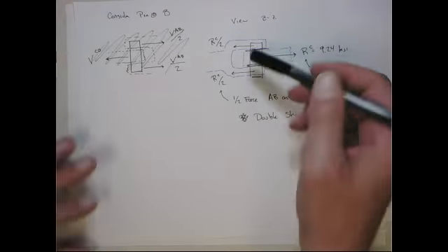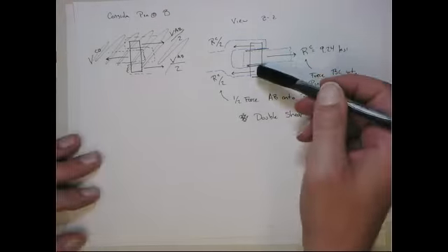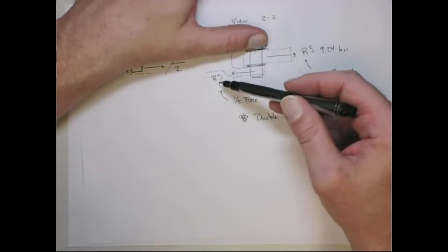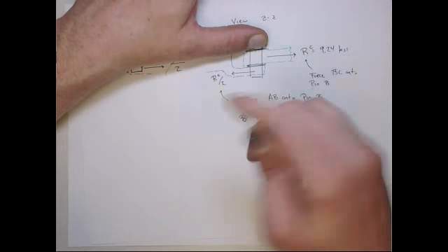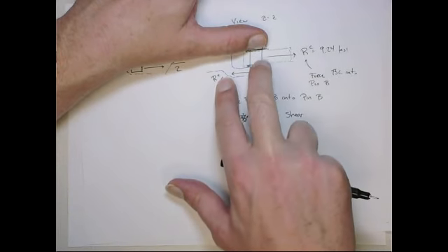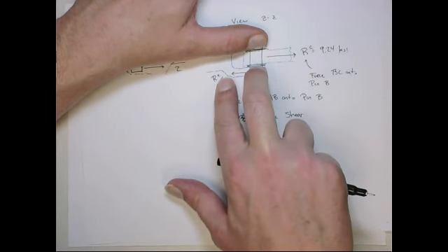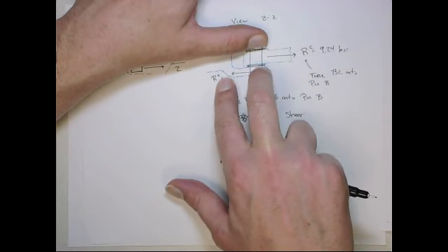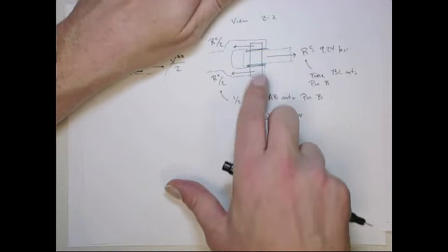So we did a double shear problem before. You see, you actually will get the same stress on both areas. The nice thing about the double shear is, if this were in single shear, this force here would actually be RC, equal and opposite, like at pin A. Then you would have the entire force at RC acting over this area. When it's in double shear, you get half.